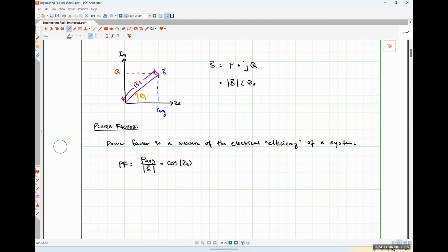We pay for the power that we consume or convert into heat. And then there's that leftover reactive power that's just getting sent back and forth between the source and the load, right? So even though they had to pay to generate that, we don't pay to consume it, because it always gets sent right back to them.